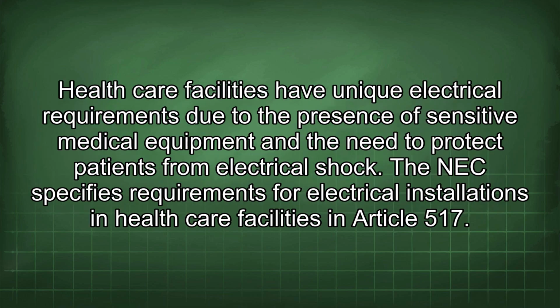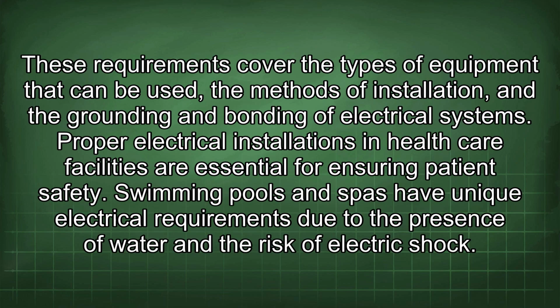Healthcare facilities have unique electrical requirements due to the presence of sensitive medical equipment and the need to protect patients from electrical shock. The NEC specifies requirements for electrical installations in healthcare facilities in Article 517. These requirements cover the types of equipment that can be used, the methods of installation, and the grounding and bonding of electrical systems. Proper electrical installations in healthcare facilities are essential for ensuring patient safety.